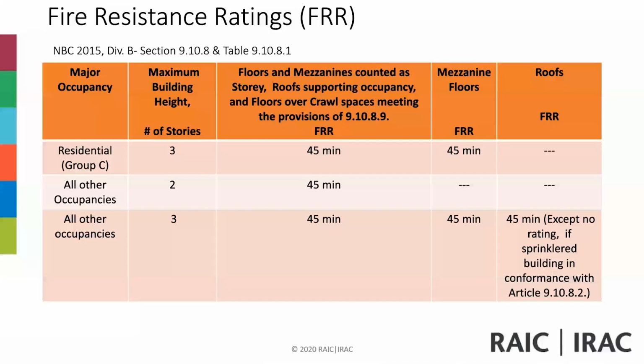Specifically for your firewalls, your party walls, fire separations separating two buildings, definitely non-combustible materials. However, you need to look up some other conditions that give you those. Fire resisting tables are specified in section 9.10.8 and table 9.10.8.1. So look up subsection 9.10.8 and table 9.10.8.1.